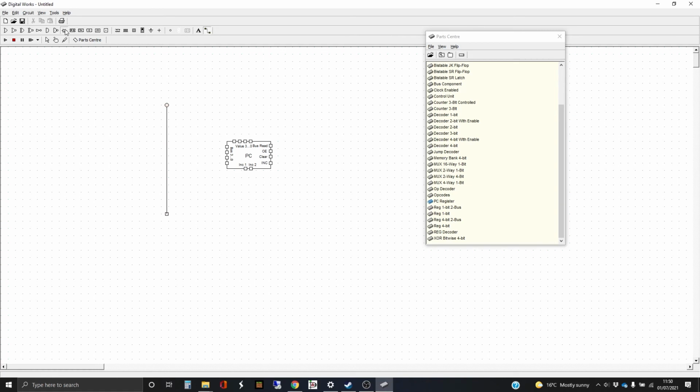And then I need a way of actually putting information onto the bus. So I use a tri-state buffer. What I do is I leave a bit of a gap so that I can do a cut and paste and they just fall into place. Then I'm going to put another gap to help this process of cut and paste. I'm not going to cut that up because I need to connect all 4 of those together. I'm just going to group select that, do Control C, Control V 3 times, and there's our bus.